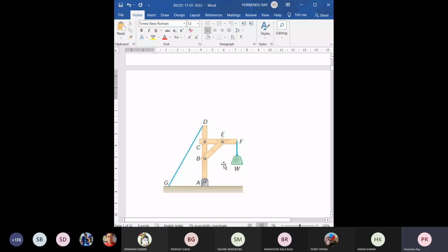Yes, sir. This is the overall framework. These joints are not welded joints. These are pin joints where rotation is allowed. Now, if there was some welding, the vertical post welded at the ground with some metallic heavy plate, then definitely you would not require this support member. Another welded hand like this, the member CF, it is welded at C. But it is like your shoulder, there is a shoulder joint, and when we apply some force here, your shoulder will allow this rotation so that your hand is not remaining in its horizontal stretch condition, it is coming down.